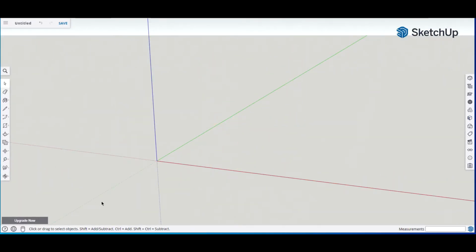So let's first start off by drawing the wall by selecting R for the rectangle tool. We're going to go to the origin, and we want this on the green, so left arrow key. And we know that my wall is going to be 8 feet high by 6 feet long. It looks like the first dimension will be the length, which will be 72 inches, comma, and then we know the height, it's 96, or you can type in 8 apostrophe, enter, gives us our wall.